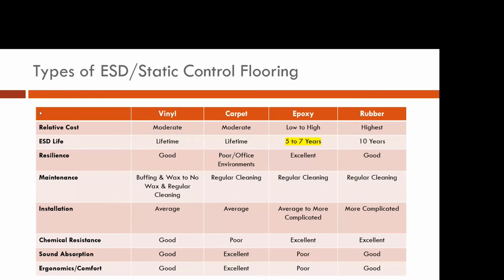We always recommend using a floor cleaner, regardless of what the material is, that has ESD properties built into it, so that no matter what, you're enhancing the ESD properties, and you're not going to put something over it that could cause a non-ESD material to leave a residue, which would act as an insulative barrier. Vinyl, buffing and waxing to no waxing.